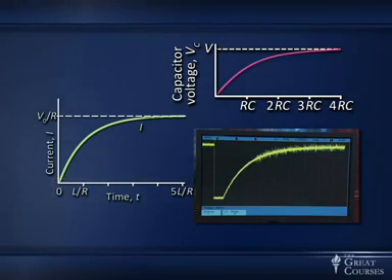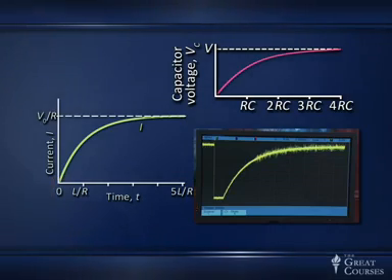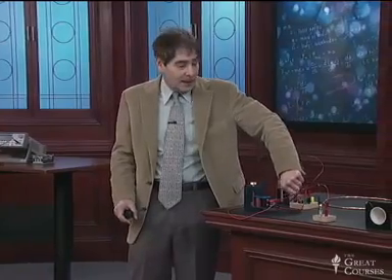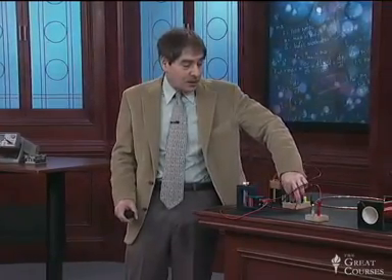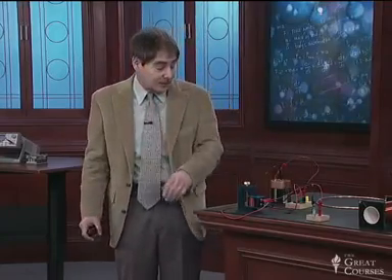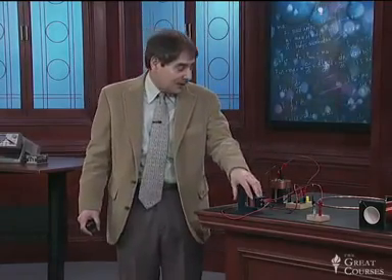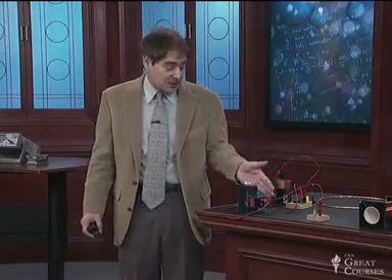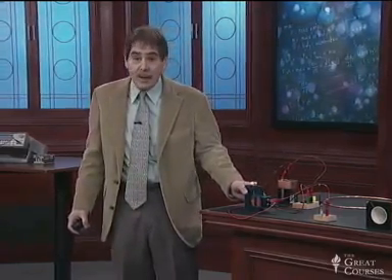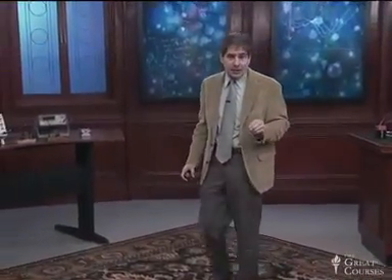So there's a characteristic time, and I've plotted on the bottom axis of that buildup curve the time in characteristic times. In the case of this circuit, the characteristic time is very short, so the light bulb essentially comes on to your eye immediately. But it really is taking some time as determined by this inductor and the resistance in the circuit, which is also, in this case, just the resistance of the wire in here. So that is the electrical property we call inductance. And it's an important thing in electric circuits.